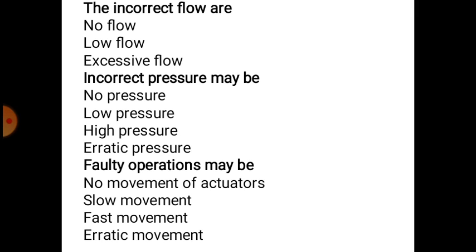Low flow situation may occur due to the following reasons. Flow control set too low. So the flow control valve is set too low, that's why the flow is less. Relief or unloading valve set too low. Flow bypassing through a partially open valve. External leakage in the system. Speed of motor incorrect. Defect in motor, defect in pump, defect in a valve, or defect in a cylinder or other elements. So these are the reasons for low flow.